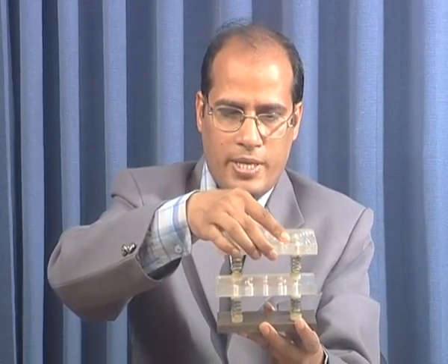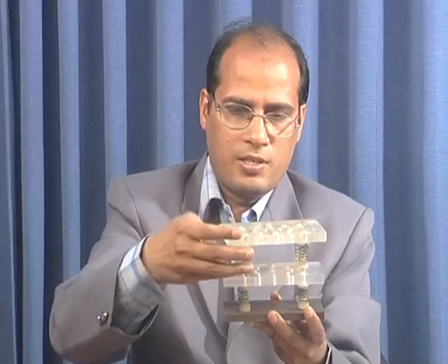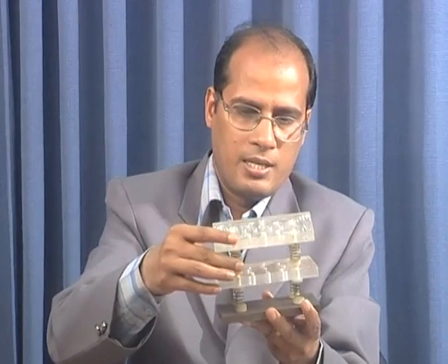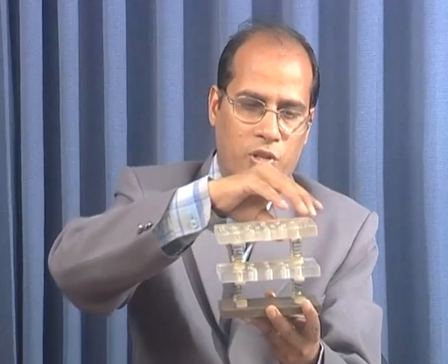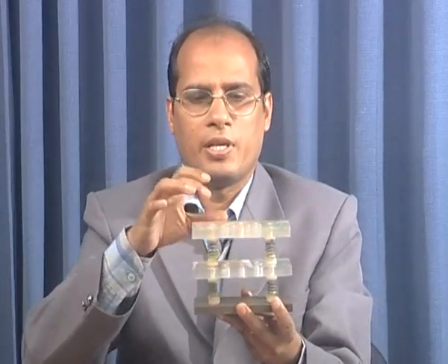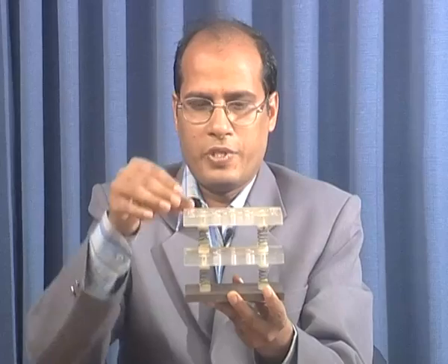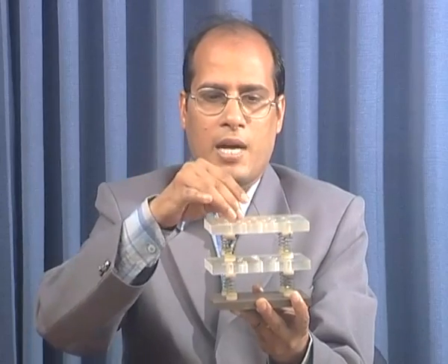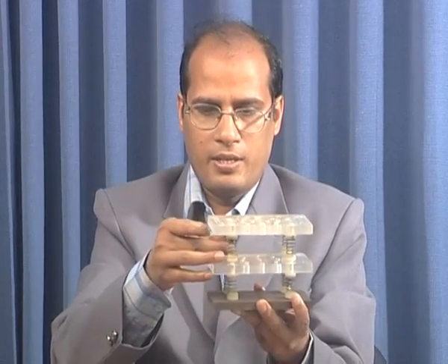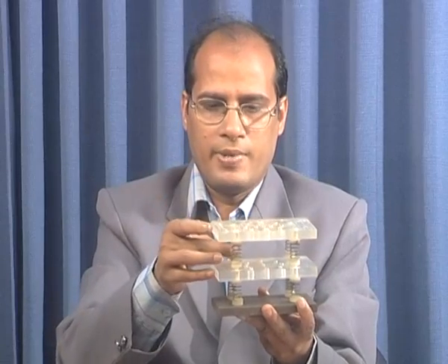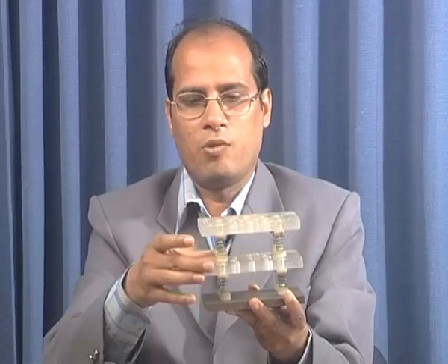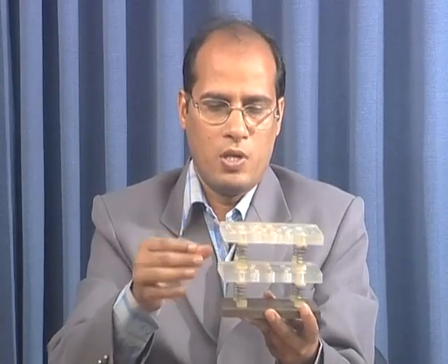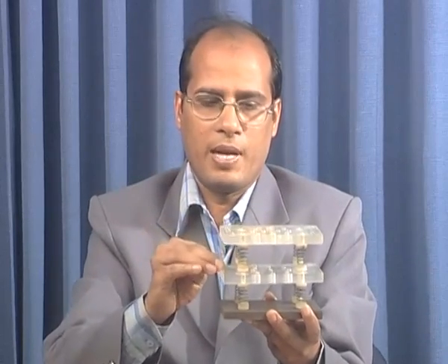You can add another spring and mass system to it. The secondary spring and mass system you can add in such a way that the frequency of excitation of the external or disturbing force should be equal to the natural frequency of the secondary system. In the secondary system, let the mass be m2 and the stiffness be k2, then the frequency of excitation should be equal to root over k2 by m2 to absorb the vibration of this primary system.